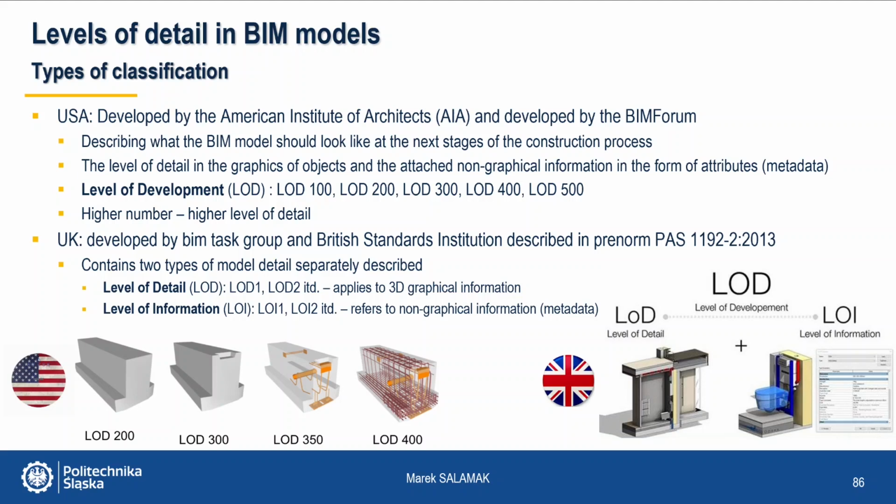This classification applies only to graphic data and is used to describe the minimum level of detail in the graphics of modeled 3D objects. The level of detail of non-graphical information is determined by an independent LOI classification, abbreviated to level of information. For example, LOI 1, LOI 2, etc.